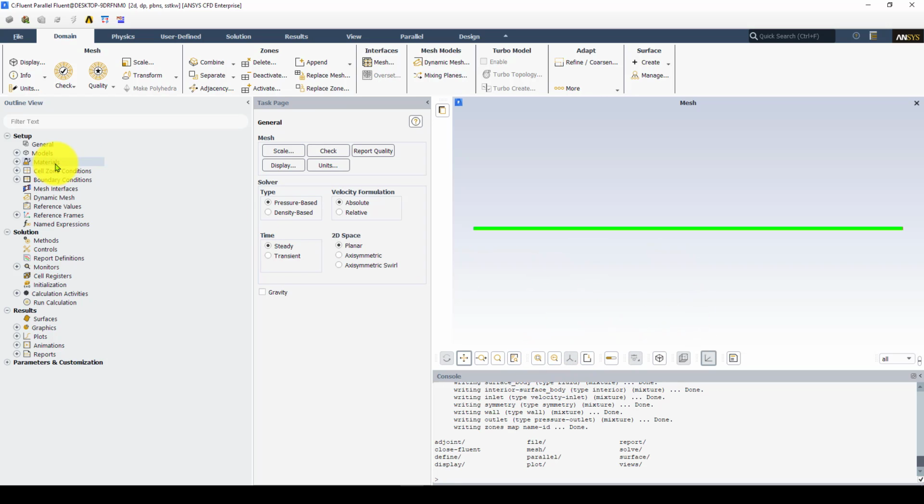Okay, so let's go here. Probably the tutorials I gave you do everything here in the ribbon. I prefer to work here. Now it's my vertical approach. Okay, so I'm used to this one. This is a new setup, that order that they have in Fluent. So let's work here. You go into general, you set up some parts of the physics, the general.